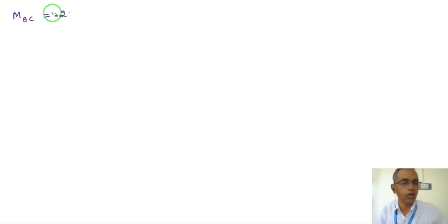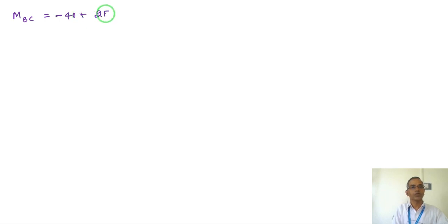Then let us go to MBC. MBC, which is MFBC, we have as minus 40 plus 2EI by L, length is 4, 2 theta B, 2 into 26.67, plus theta C, which is 0. BC does not have a displacement, I mean deflection.